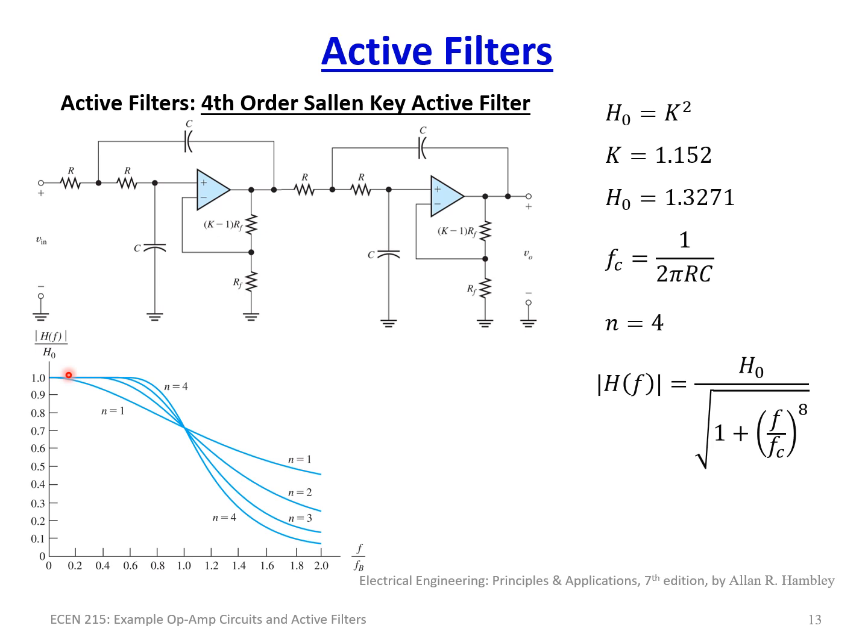If you dig into other types of filters, and there are various different kinds, sometimes the pass band, as it is known, which is this part here, is not flat. Sometimes it's very ripply, but they have very sharp cutoffs. So if you're not caring if your amplification is perfect here, but you want a really sharp cutoff, ideally, obviously, you would want it to be right here at 1.0 to be completely cut off.